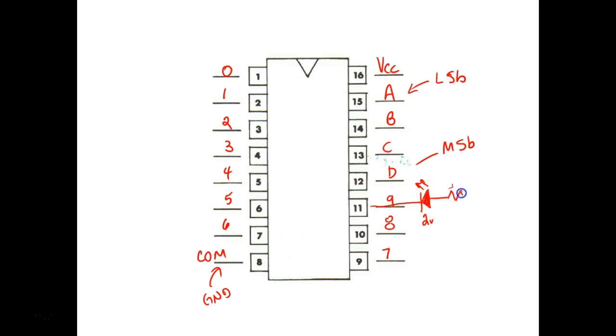So right here I have a 330 ohm resistor, which is standard. Usually 470 or 330 are very popular for LEDs. And then I have the same circuit right here. The only little difference is that on this side I have this connected up to a VCC.